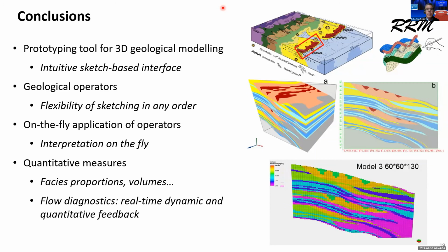in our models. The various meshing algorithms we've tried to use with unstructured grids sort of died halfway through, and it doesn't help you if you can create a complex model like this in half an hour, and then it takes you multiple tries to mesh it. That's why we went back to this really simple structured grid. You can refine it on the fly. It's always stable. It's always very fast.